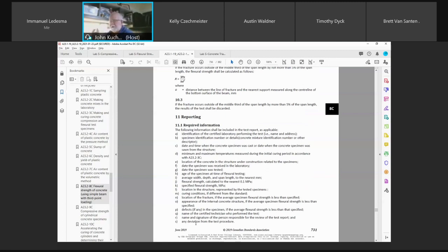So if you ever did a specific gravity test, or mass-weight-volume relationships with Natalie last year, if you had a specific gravity for clay soils in geotechnical materials of 1.8 or 3.6, there's something wrong. You can't have that for clay. So then you would know you did something wrong. Same thing here, okay? I'm not going to give you anything that doesn't look realistic. Not intentionally anyways. I may do it by accident, okay?